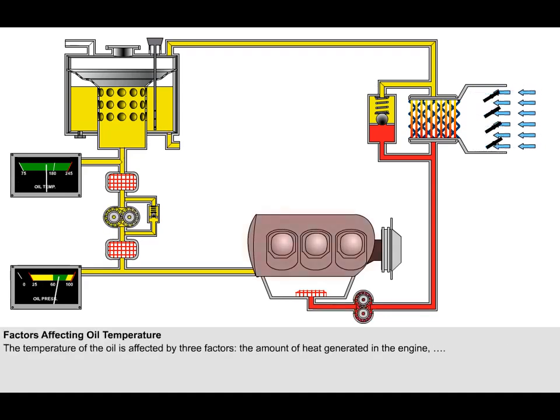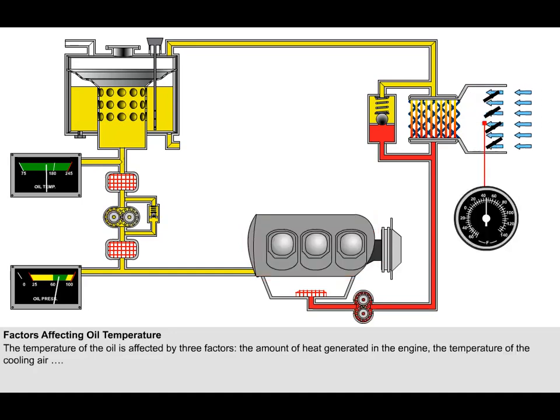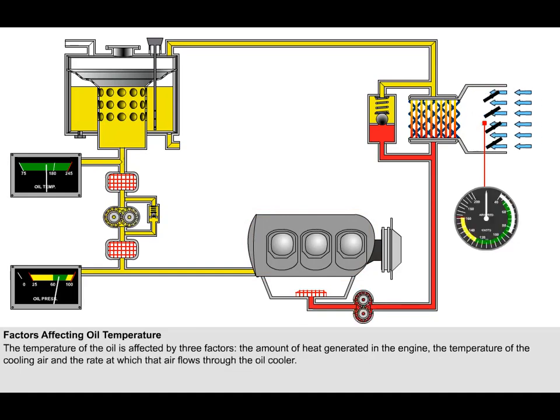The temperature of the oil is affected by three factors. Firstly, the amount of heat generated in the engine, which is proportional to engine power output. Secondly, the temperature of the cooling air. And thirdly, the rate at which the air flows through the oil cooler.